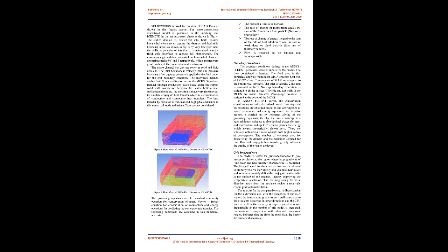It is indeed crucial to develop an efficient cooling method, particularly when the conventional heatsink is inadequate to meet the high heat flux requirements. Liquid-cooled microchannel heatsinks and coolers have been shown to be a very effective way to remove high heat load. A large heat transfer coefficient can be achieved by reducing the channel hydraulic diameter.